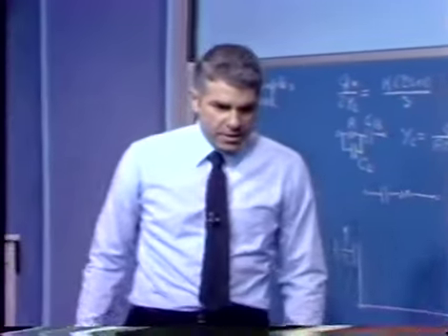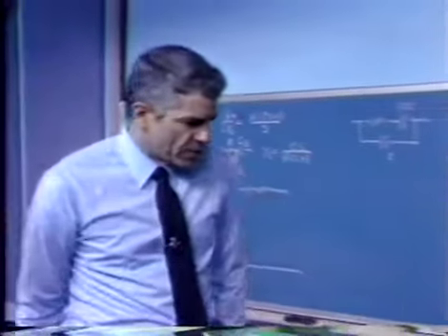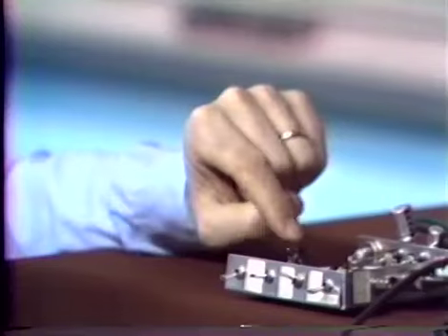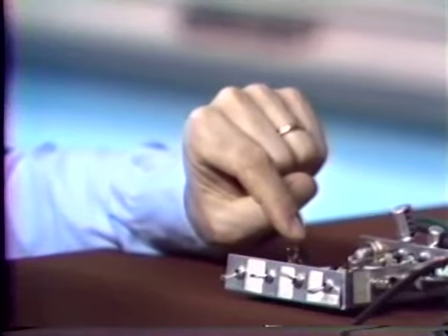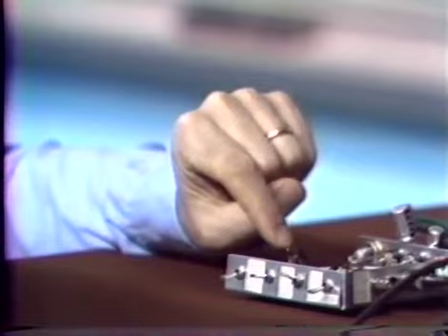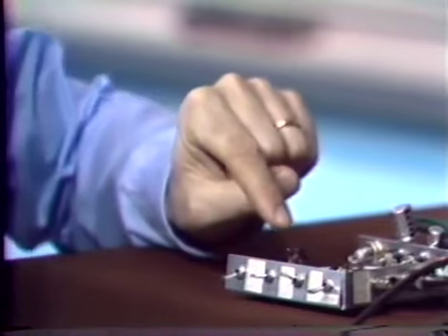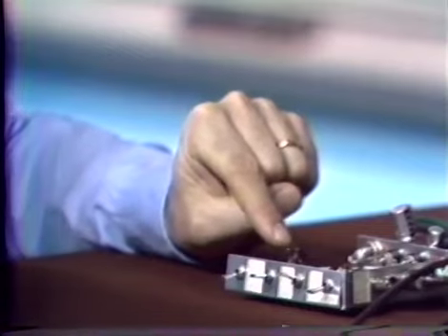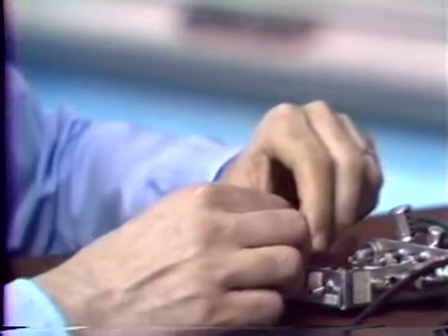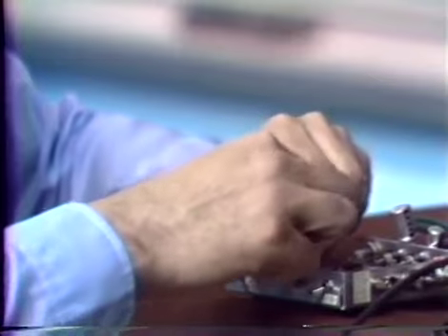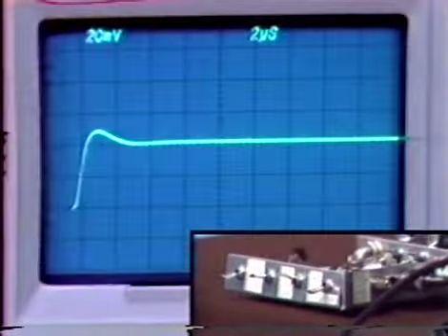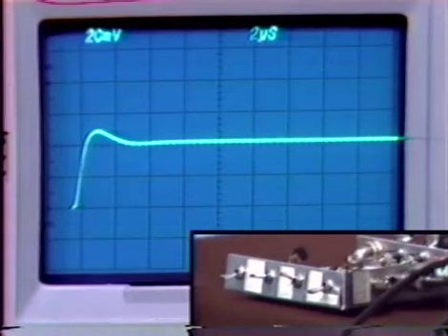And in this particular setup, we've chosen our small capacitor here to be roughly 1/10 of the value of the big capacitor, and that results in a very good compromise between maintaining stability in the minor loop and yet not compromising the stability of the overall loop. So let's now add that capacitor. When we do that, we notice the basic transient response remains the same.